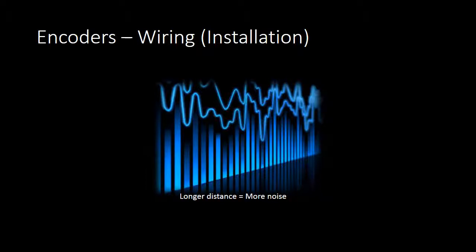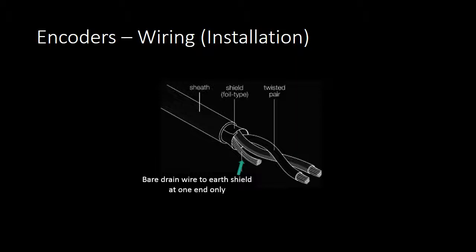The majority of signal transmission problems will involve electrical noise, with the problem increasing the greater the distance that is covered. Using proper shielded cables and proper earthing is important. Many problems can be avoided with good wiring and installation practices. Maintain continuity of wires and shields from the device to the controller, avoiding the use of terminals in a junction box.